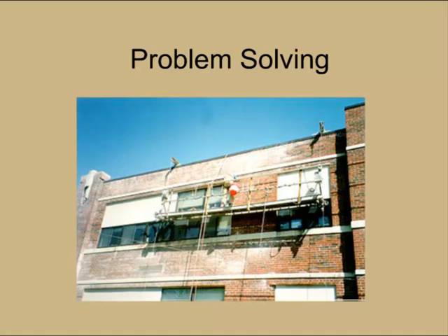Eventually, we got involved in the facility. We did some more exploratory work. We found out that the through-wall flashing system was in very, very rough shape. There were severely corroded lintels, a lot of underlying issues that was never addressed. They had to fully replace some lintels, redo that through-wall flashing system, redo the tuck pointing yet again, but that's spending good money after bad. They spent a whole lot of money on that tuck pointing 2 years in a row, but they never addressed that cause, the cause of the problems.